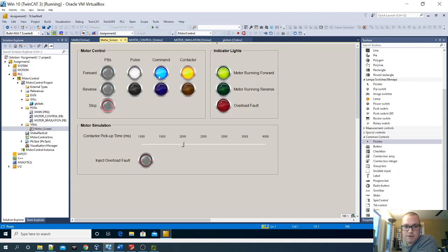All right, there's my pulse, my command, 2 seconds later. Yeah, okay, so notice the pulse went away after 3 seconds. But the motor command continued because we want to keep telling the motor to go. And as long as we're still telling the motor to go, the contactor remains closed. And the contactor and the motor running are basically exactly the same signal because the latter was just if this one's on, then this one's on. All right, or if this one's closed, then this light is on.